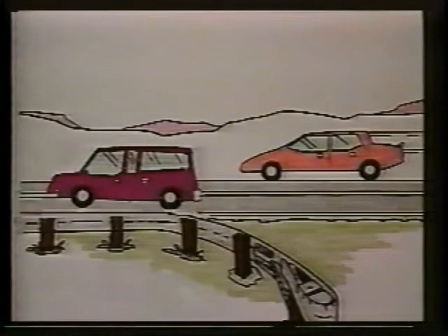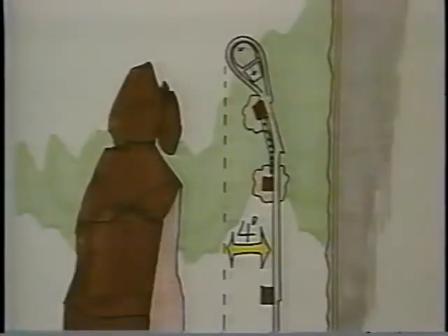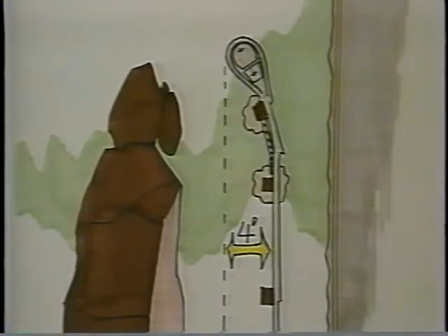Flare characteristics of the BCT are critical to its proper performance, particularly with the smaller vehicles that might impact the system. Head-on hits with unflared roadside barriers can cause severe damage to these smaller cars. Flare for the BCT must be parabolic with a 4-foot offset from the tangent section of the railing.